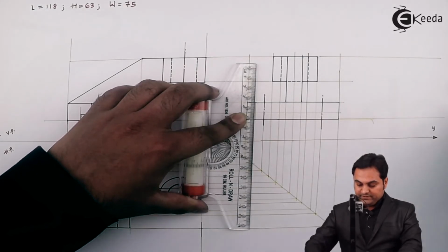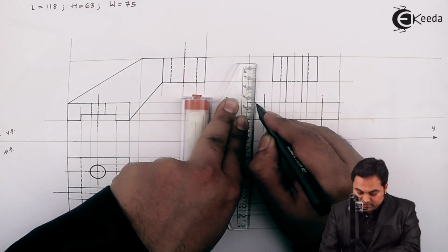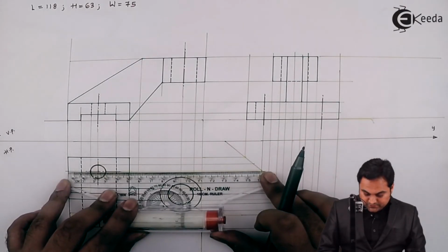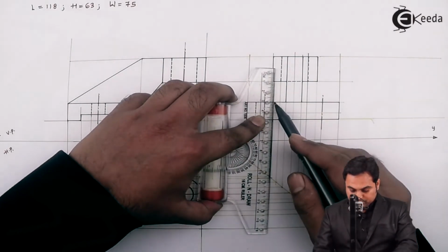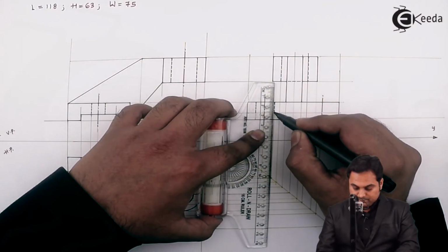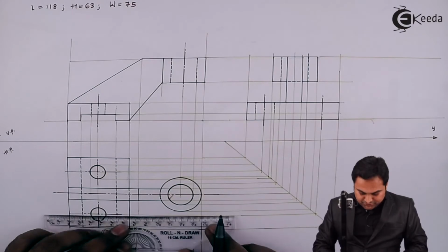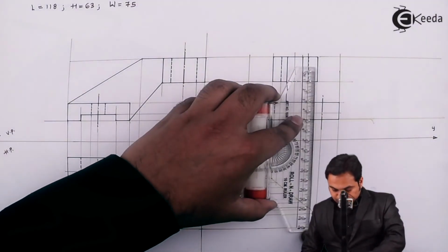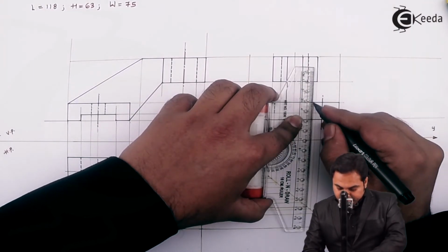And here itself I'll be making it dark so that we can understand. Now the holes are only up to this plate, and then the other part of the circle. Projecting it and then making it dark. So here we have the center line, then projecting the other circle, and then directly making it dark, since it is a hidden line.